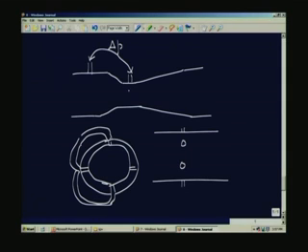Here also you will have several holes on the periphery, all of them connected to this tap, and here I have several holes which are connected to this tap. So, it is the average pressure around the periphery which is normally measured in the case of an installation like this.